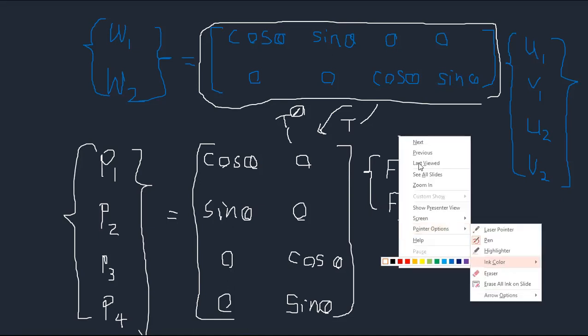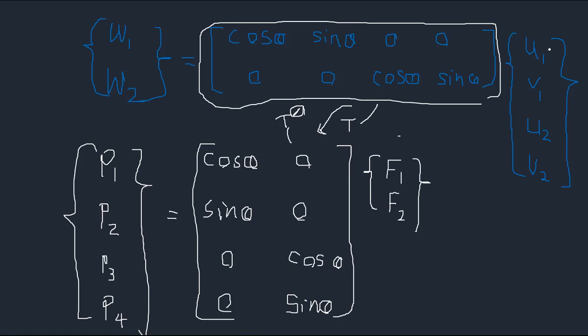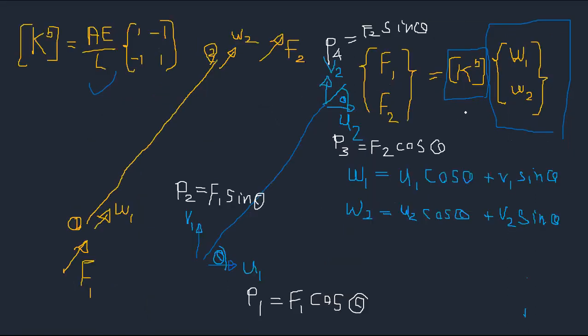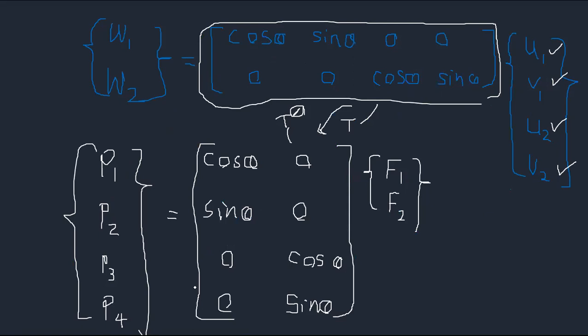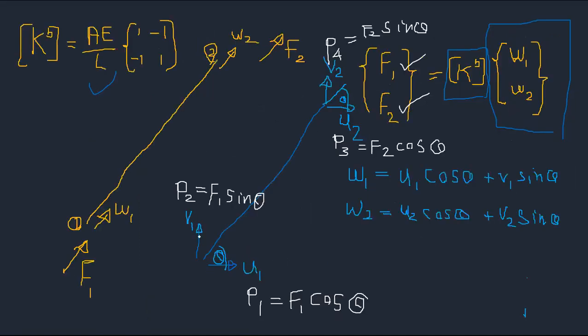This step is very critical. Once you take the output from the FEM, you can directly take those into the local displacement and then find the local forces, the tension or compression. That's quite an advantage in a truss. That's what we need. So these are the global forces at the nodes, the nodal forces, and those are related to the tension or compression.